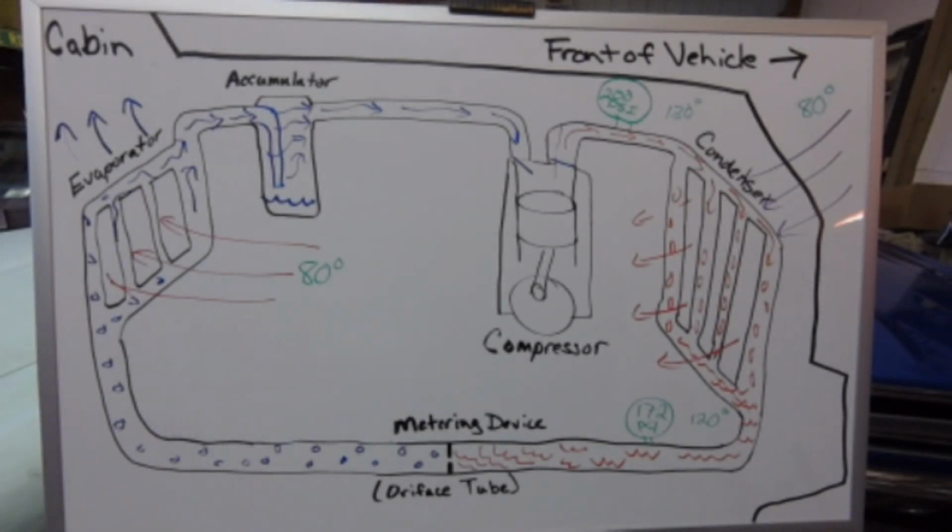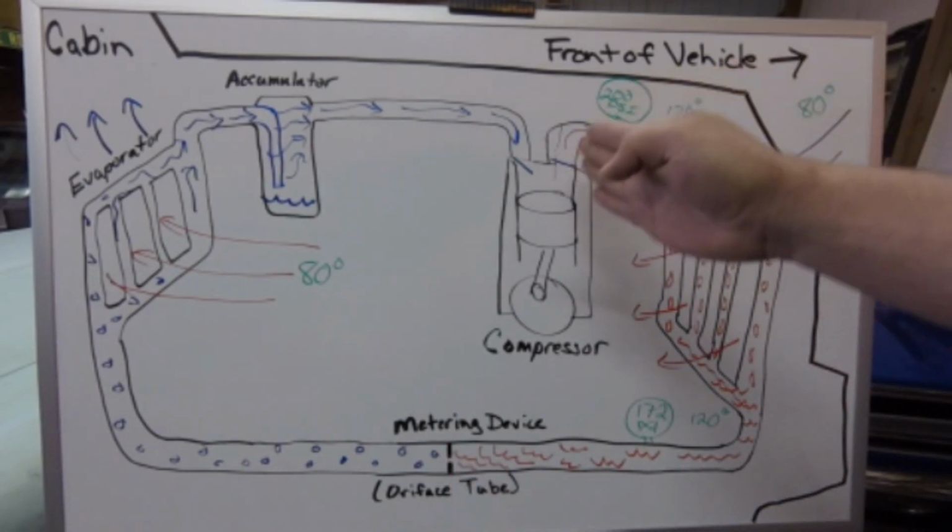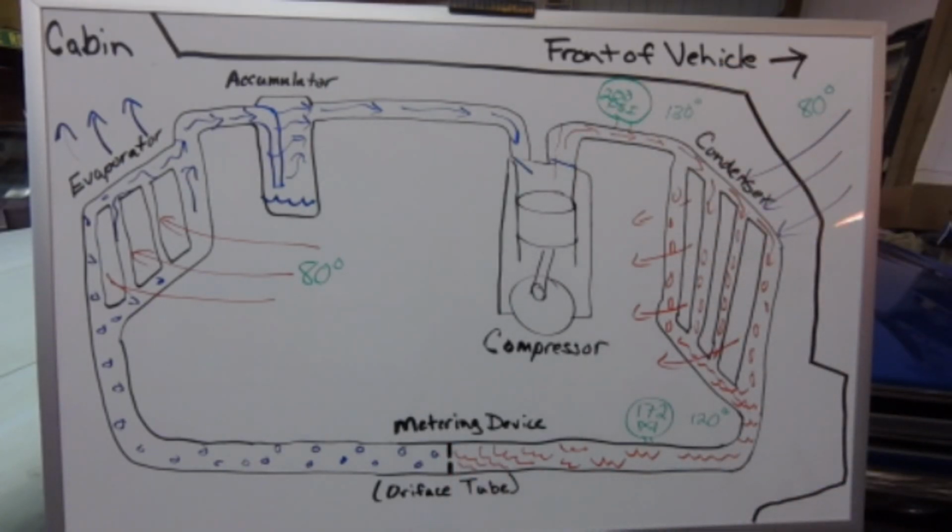What we have now managed to do is remove a lot of heat energy from the refrigerant, but we have actually not changed the sensible temperature of it very much. So we have much less heat quantity here than we did here, but our actual sensible temperature is not far away from each other. And that is because of the high pressure on this side of the refrigerant system.